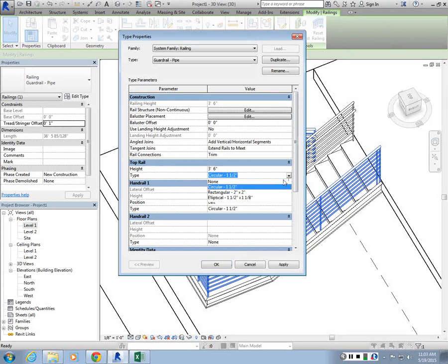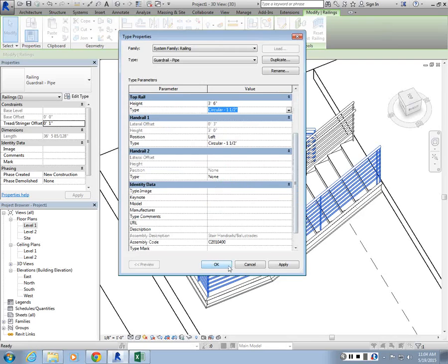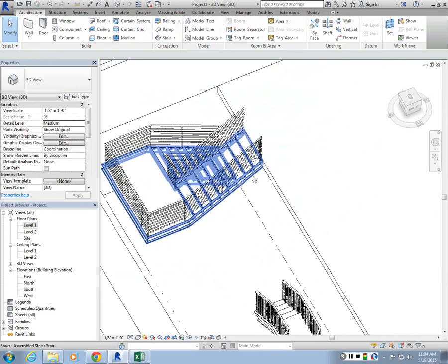So these are all objects, right? So we can control the section profiles as well as the dimensions of it. I mean, of course, there's an unlimited amount of variation, but they just come in with some presets. And later on, when we get to families, if you want to create your own staircase railing, you'll be able to add another profile here or another dimension. I'm going to hit OK.